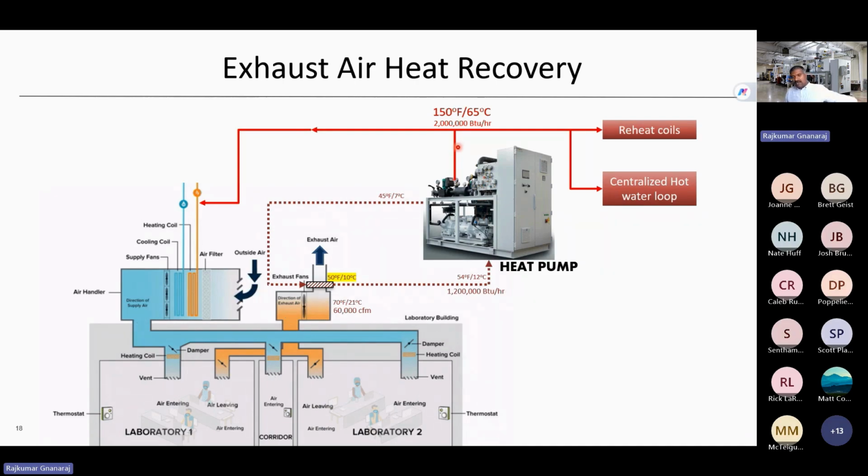So the central plant heating load will go down. So instead of changing the central heating plant in a campus from a steam-based hot water system to a heat pump system, if we can work backwards, building by building, and reduce the load in each building with the help of a heat pump, definitely your central plant heating load will go down.